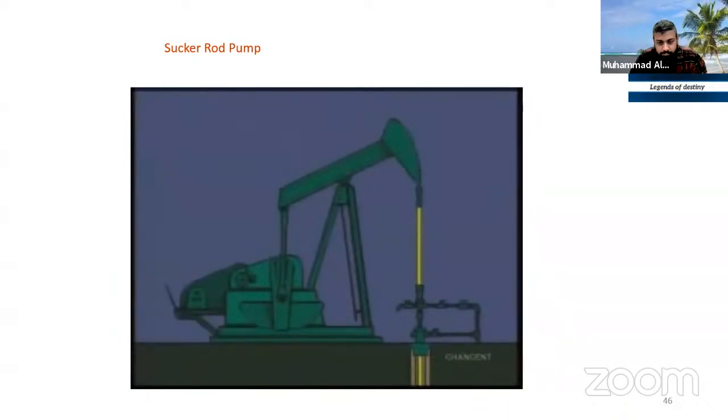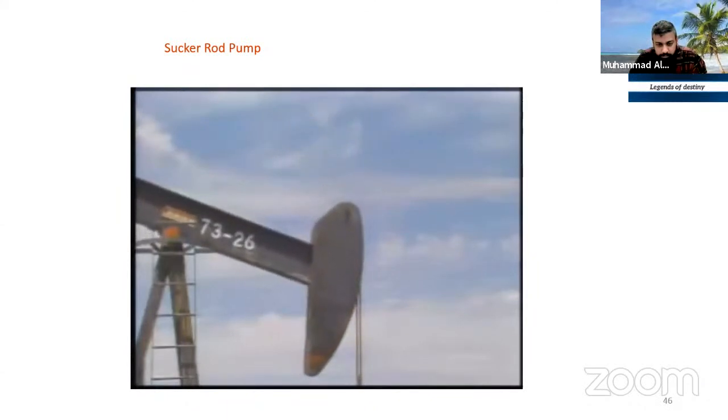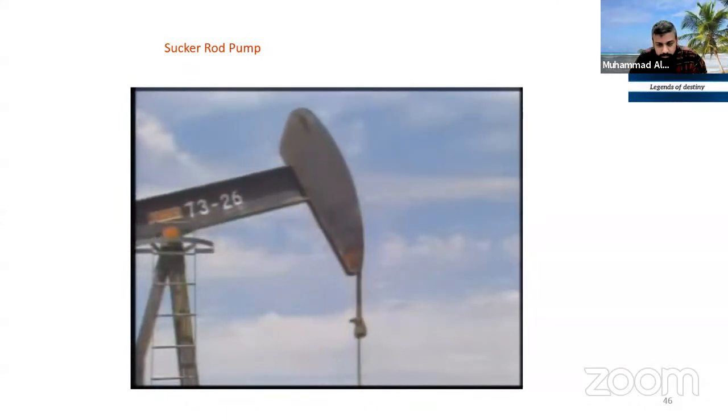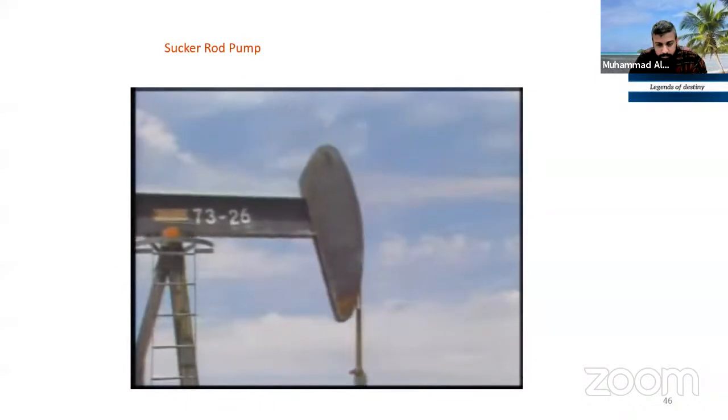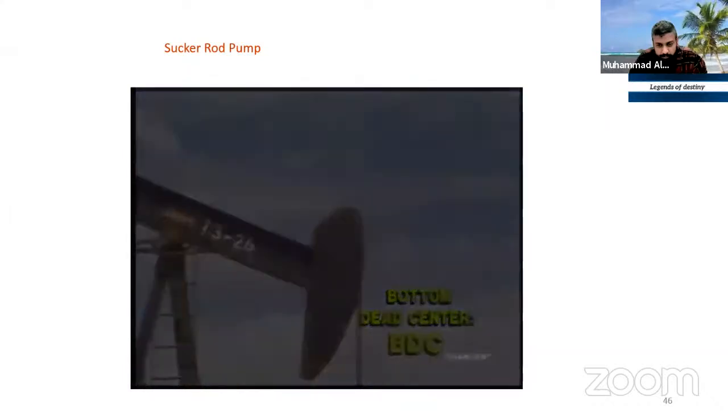As a rule of thumb, polished rods are usually 2 or 3 times the actual stroke length. This allows them to be reversed and reused if corrosion or excessive wear occurs. The stroke length of the polished rod can be measured at the top of the well. When the horse head is at its lowest point, known as bottom dead center or BDC, the polished rod and rod string are at the bottom of the downstroke.